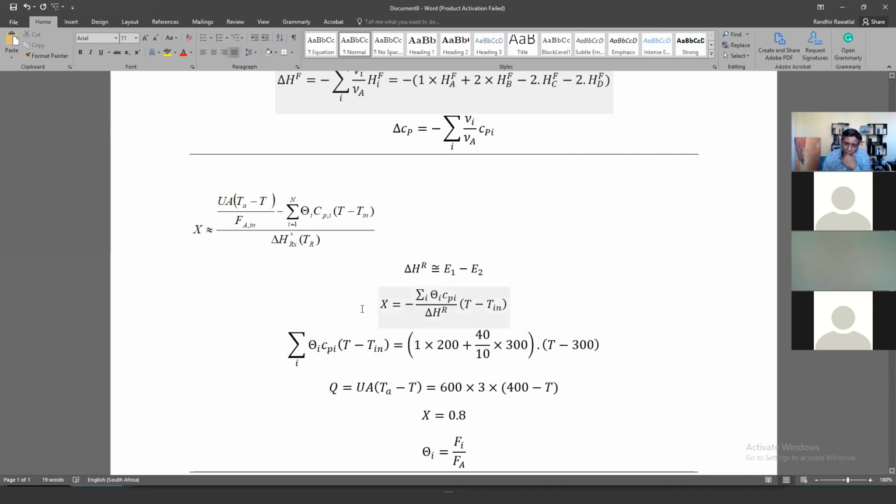If I look at the equation, there are things we can do here. So far we've fooled around a bit with the inlet temperature. We can't really do anything about the heat of reaction. That's nature's constraint, that's what we are trying to navigate. But here we can think about something: our inlet flow ratios. You would say, what are you talking about? Do you want to add product to this? That's not going to help. Well, we don't know. It might help us navigate a bit better.